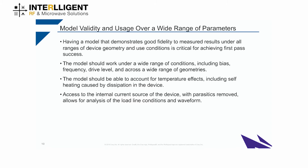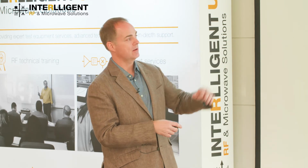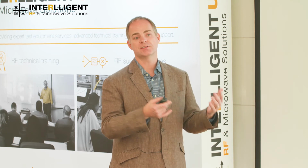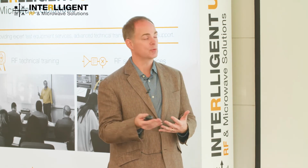Also, the model needs to be able to account for temperature effects. So as you dissipate more power in the device, obviously it's going to self-heat. The junction temperature is going to go up, and you're going to see the effects of that on both the capacitances and the intrinsic current of the device. That needs to be accounted for in the model so that as you drive these things, you are actually seeing the degradation that you're going to see due to thermal.